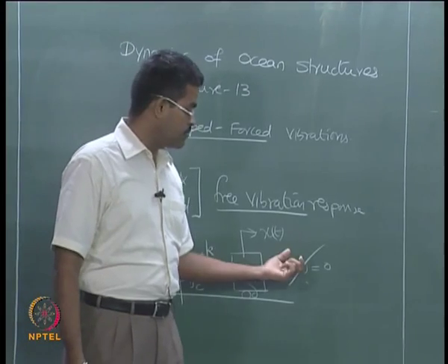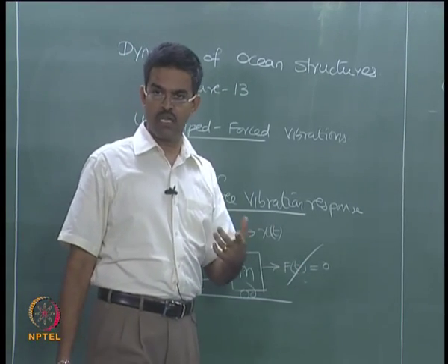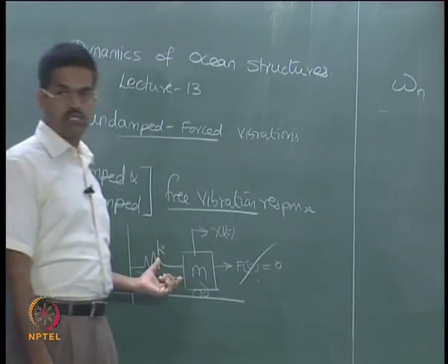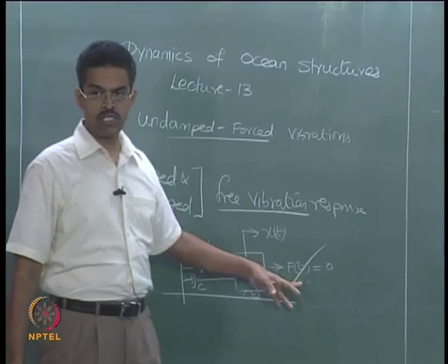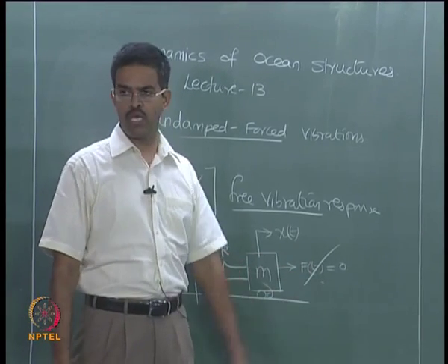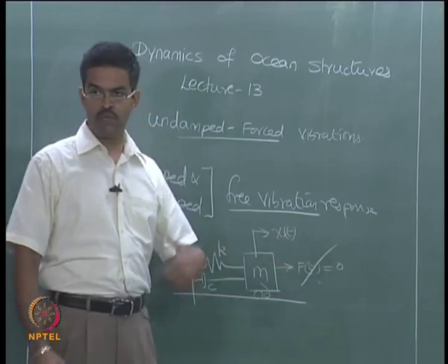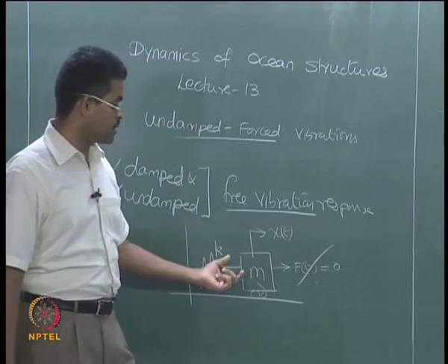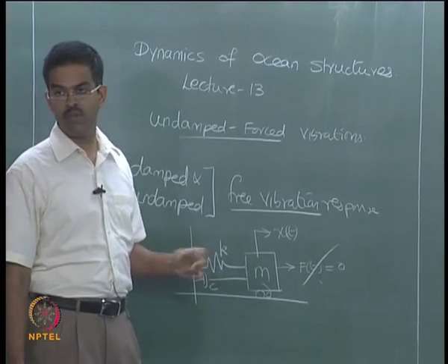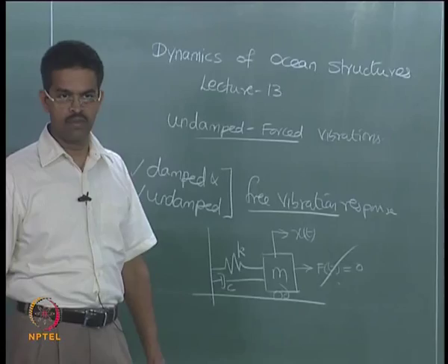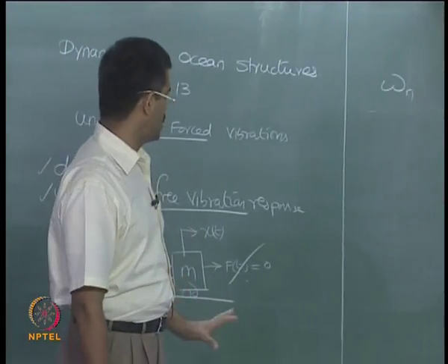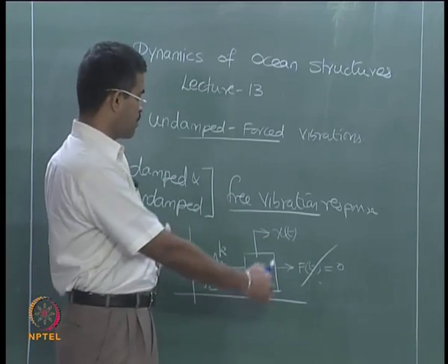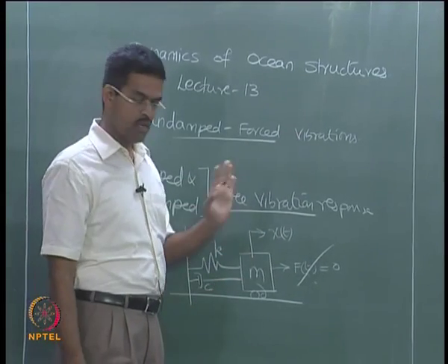by the excitation frequency which can be present in the external agency or a force, because the moment I have an external force present in the system which is also a function of time, because we are talking about the dynamic loading, then this will also have a frequency of vibration. If that frequency at which this is exciting matches with the natural characteristic of the system, then the response of the system will be different from what we have so far seen. So, I want to isolate this discussion initially, that let me not have any forcing frequency in the system, I will take only the characteristic of the model itself and estimate the natural frequency which we studied.